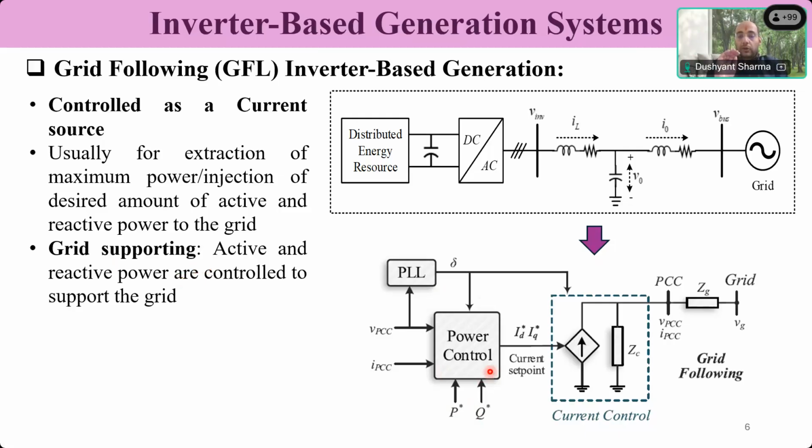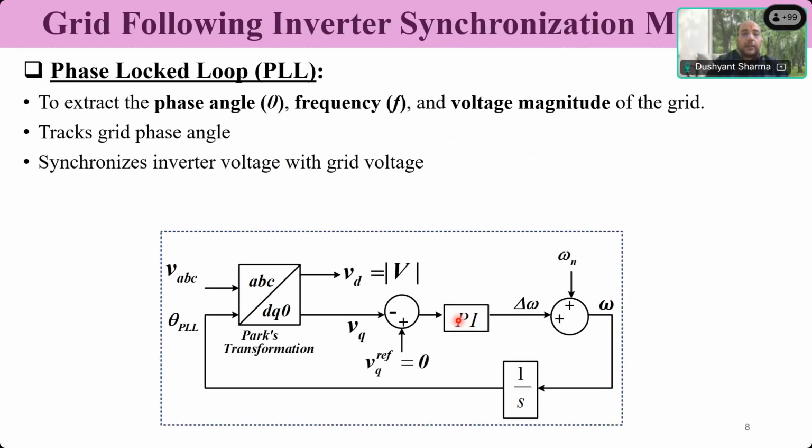It will only be governed by the control algorithm that we use. So for an inverter, it becomes very important what the control mechanism is. And that control mechanism is usually, for a three-phase inverter, carried out in the D and Q axis domain, not the ABC domain.